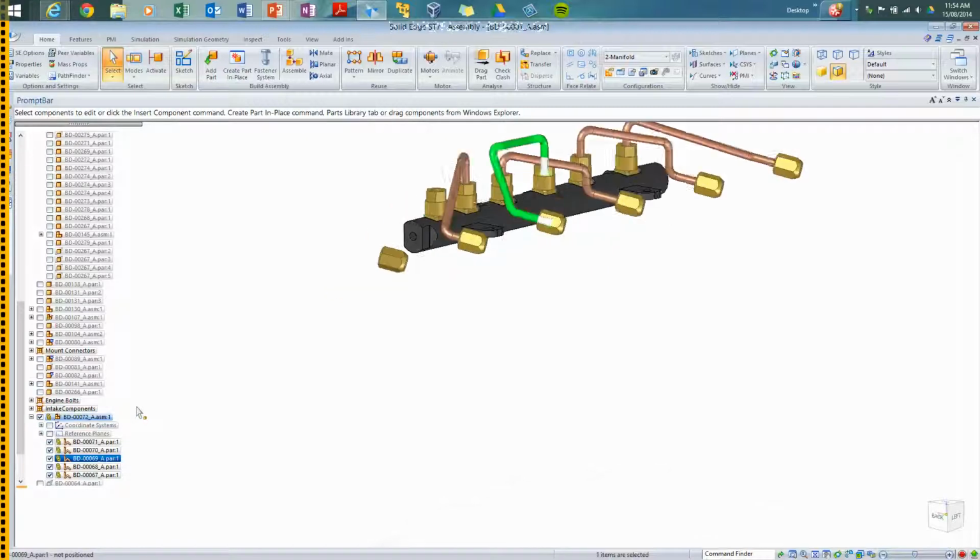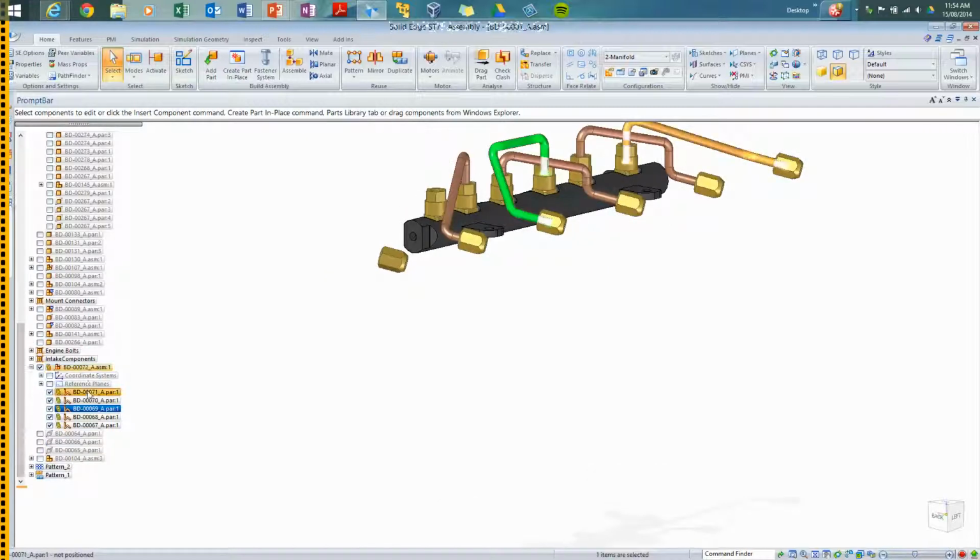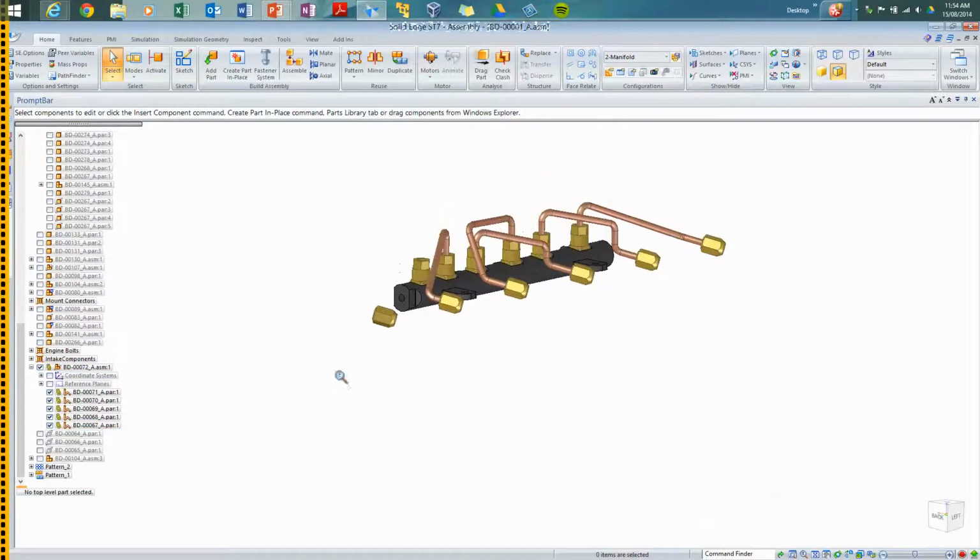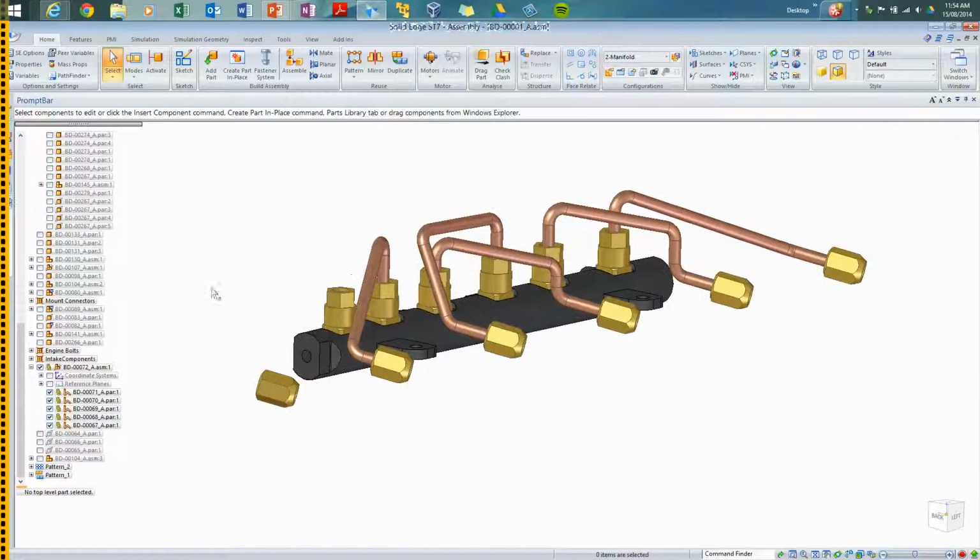And if we expand out this structure slightly, you'll notice that actually this sub-assembly contains nothing but tubes, and that's difficult to do, if not impossible to do in ST6. The references that you're using to create the tubes have to be in the assembly. I can't just create an assembly full of tubes that don't have any references outside the assembly. So how have they done that?